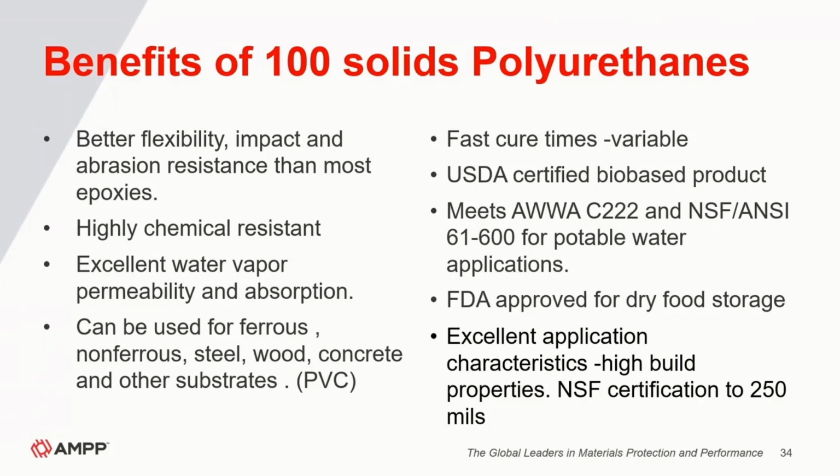Excellent application characteristics. They're high build with NSF certification up to 250 mils if you need. Generally speaking, we follow AWWA C222, which is 25 mils or more is what's required for our LifeLast product. But once again, they can build it up to 250 mils thick for different applications.